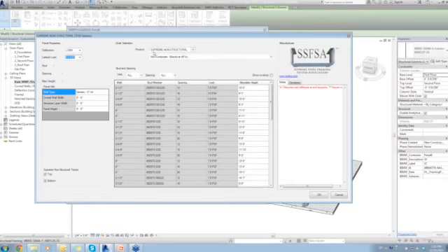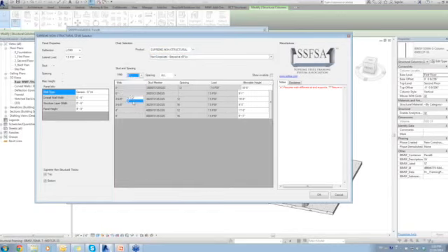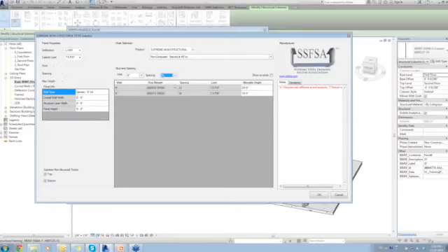the product I'm interested in using, which would be the Supreme Non-Structural Studs, my composite here, I'm going to brace it at 48 on center. I then specify the web depth of the studs I want to use in this wall, so I know it's a 6-inch wall, and then my needed spacing. You'll notice that my limiting heights chart has been narrowed down, and it gets narrowed down even further.